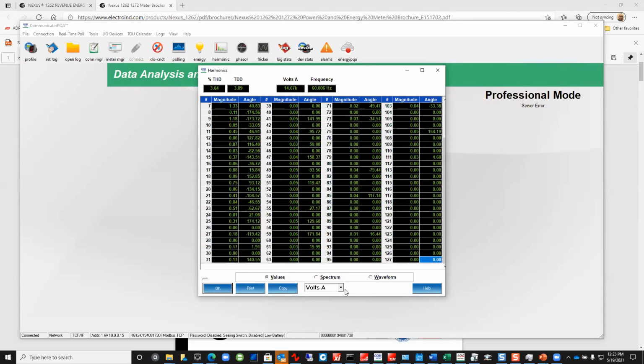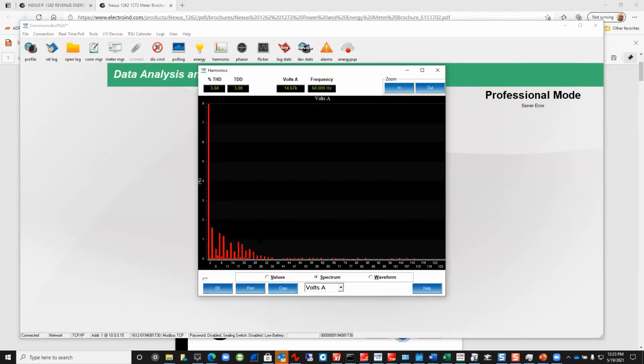And this is what it looks like from the spectrum. It's very noisy. I suspect it's my UPS creating all these harmonics. This is a typical environment with what UPSs are doing, and you really want to monitor harmonics. If you know utilities, it could create a big problem. It's basically a heating effect on the wires and inefficiencies in the system electrically. So you really want to remove these.